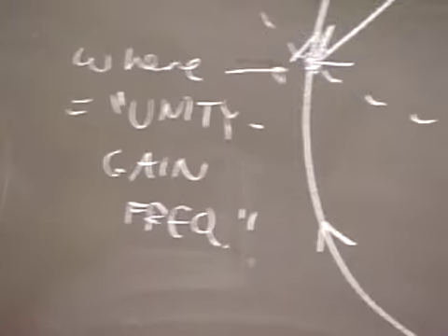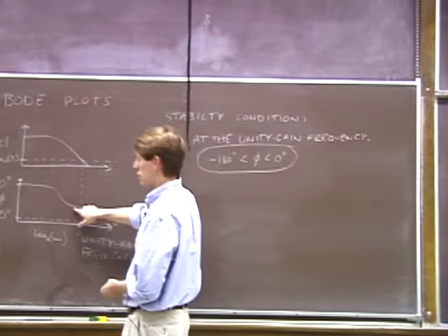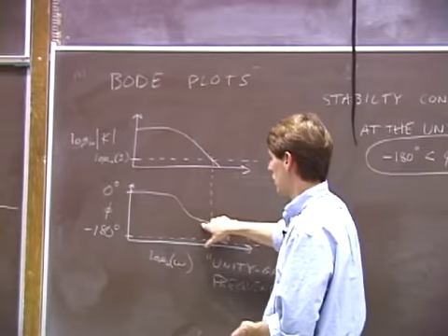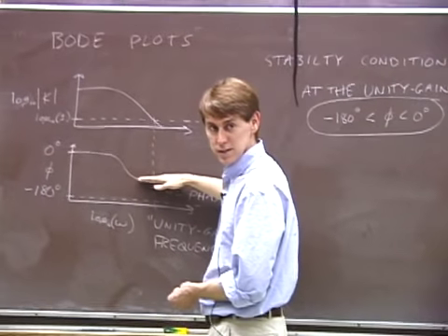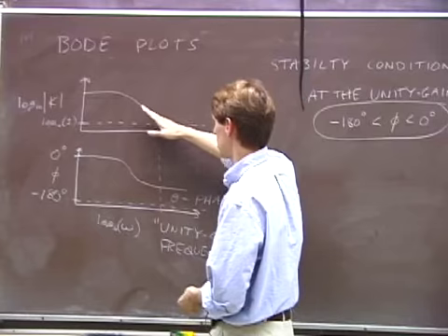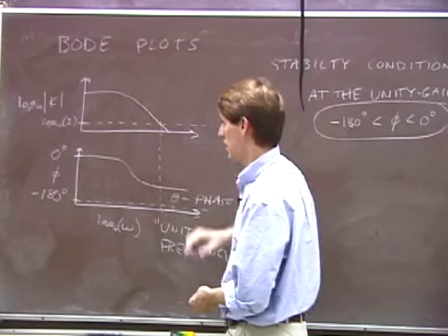Now, I'd like to point out one thing. There's a theorem, and it's related to the Kramers-Kronig relations. If any of you are familiar with the Kramers-Kronig relations, you may be able to see the connection between this. But there's a theorem that relates the phase of a transfer function, or I should say the maximum phase of any transfer function, to the behavior or its scaling in its magnitude.